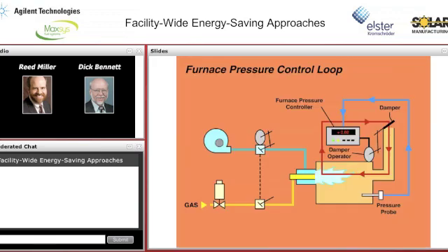Now, the way to deal with this is using a furnace pressure control system. Quite simply, a furnace pressure control system is a damper controller. They come in various forms. This one shows a so-called mechanical or clapper damper. The reason for this is that as you change the firing rate of your combustion system, you really need a flue or a stack which changes size in proportion to it to maintain a positive pressure. Now, with most flue construction, that's impossible to do. So we can simulate the effect of changing the flue size by putting a damper on it.